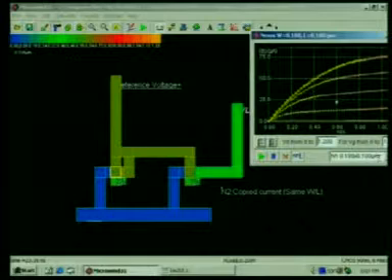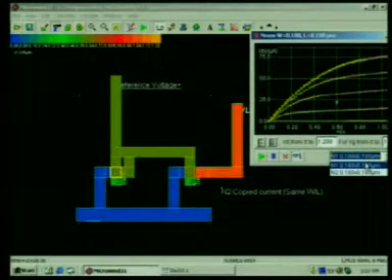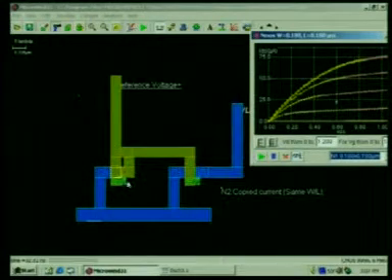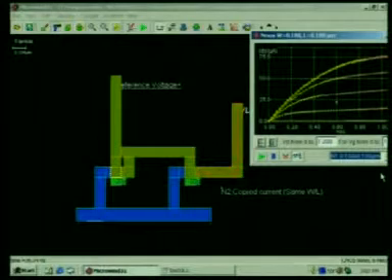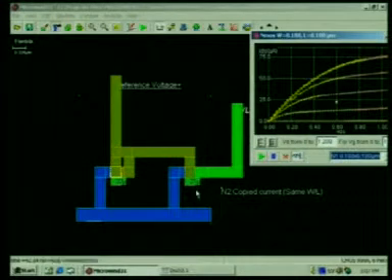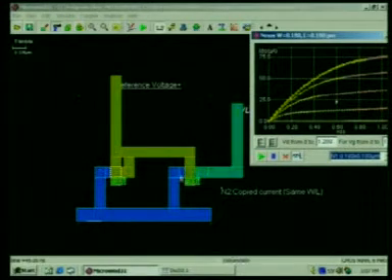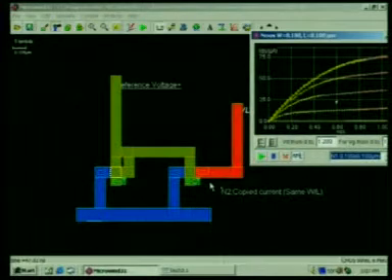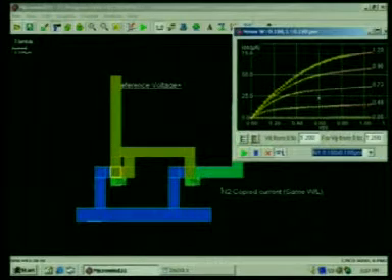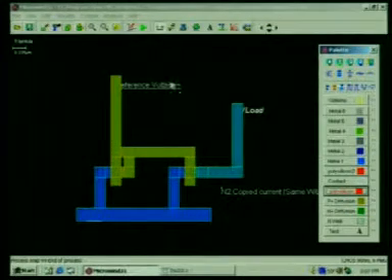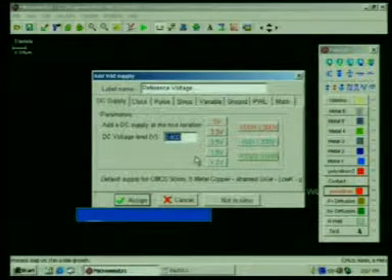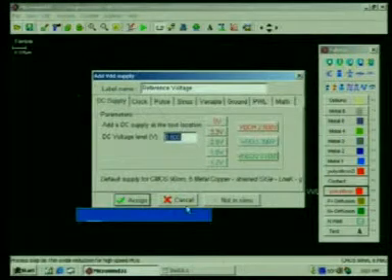So, I have applied the node voltage N2, and here I am getting 22 microampere current, I want to copy this one here. So, the exact current will be copied if the properties of this NMOS and this NMOS are practically the same, but that is practically not possible. So, that will be approximately equal to this one. And one thing about this one is whatever reference voltage you have, this one, this is 0.60. So, in this linear region, my current will be copied, you can check that.